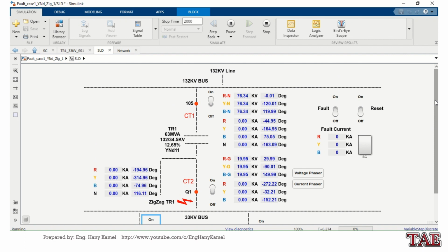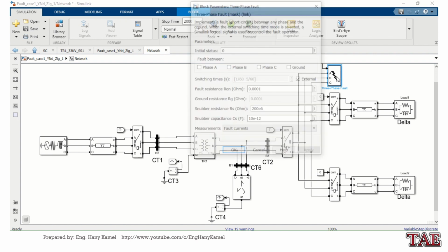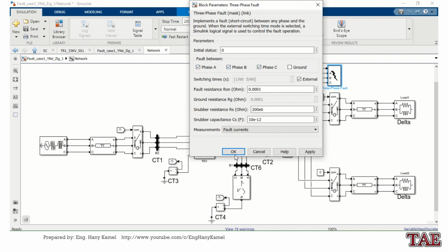So with the measurement for fault current, we can see how much fault current there is during the fault, excluding the load current. Now I will apply a fault after CT2, meaning outside of the differential protection of the transformer and the restricted protection of the 33 kV side. Here I didn't put protection for the busbar or for the feeder because I'm only interested in transformer protection. I will start with a 3-phase fault.